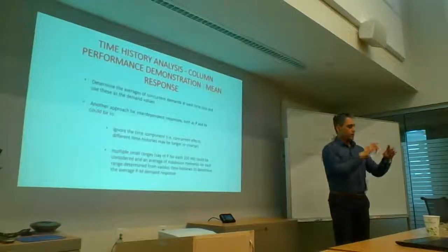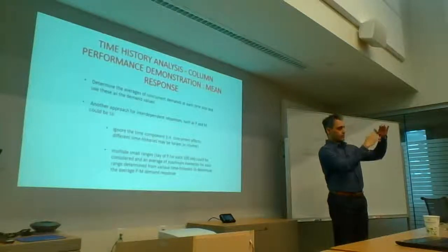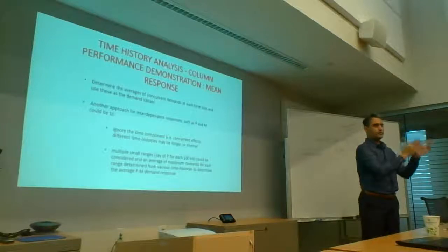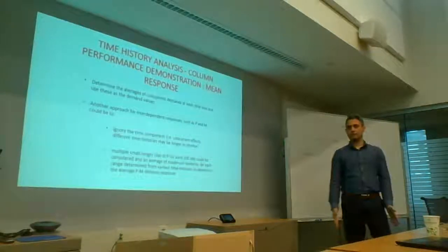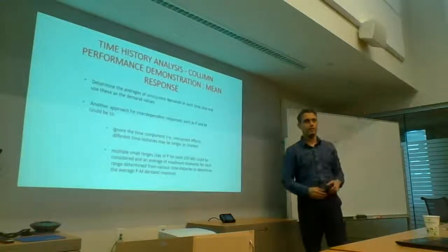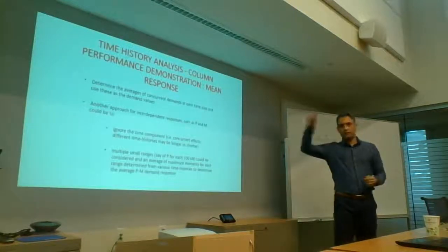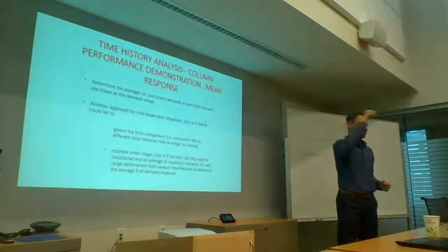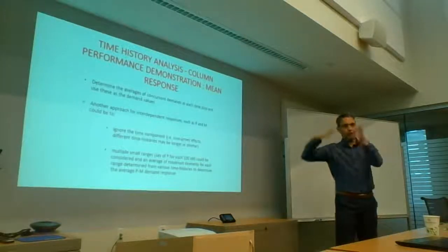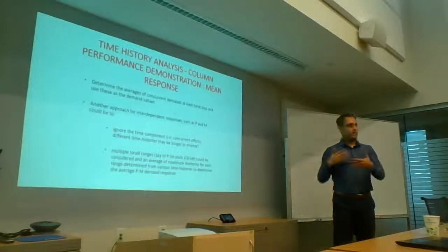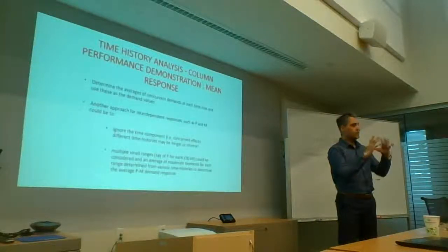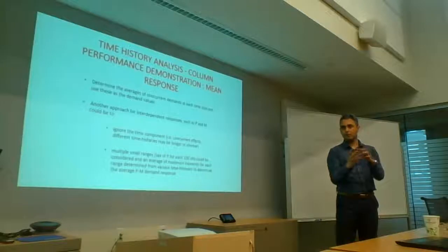You can say for 100 kilonewton intervals: 100, 200, 300, 400, 500, all the way to 5,000, for example, I've got 50 intervals. I'm going to go into each one of them and figure out what the corresponding moment is for that P value. It may happen at different times, but that is a bit more meaningful because the P and M correlation is happening within the system.